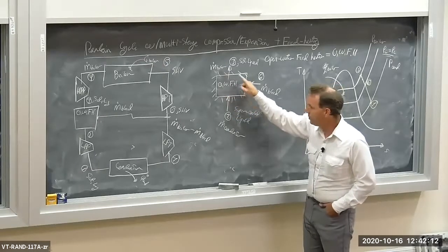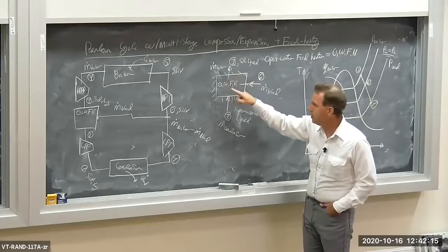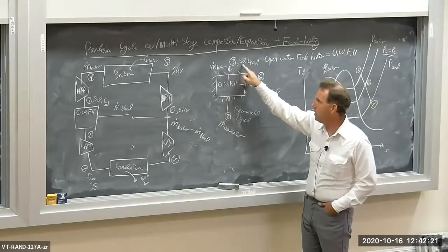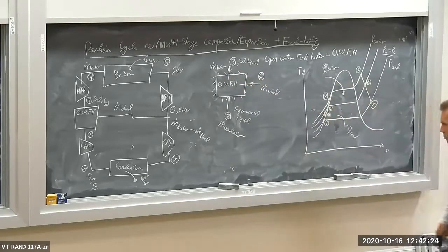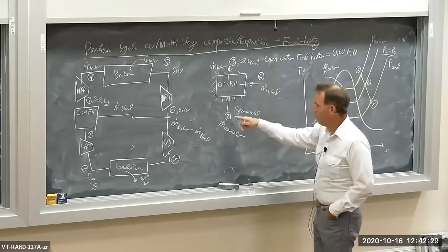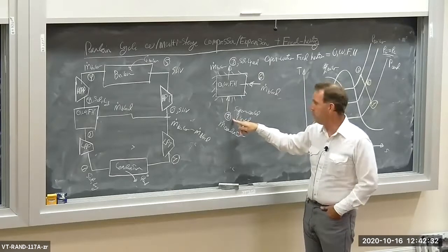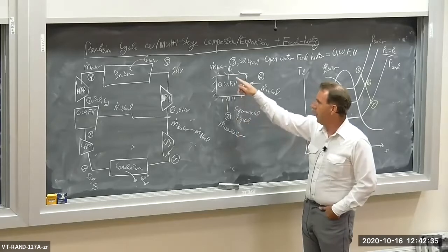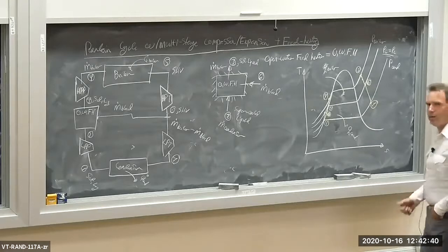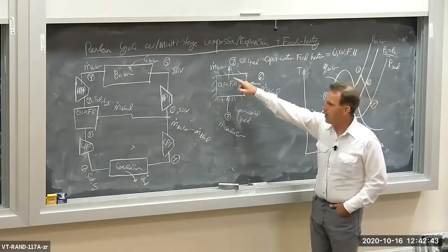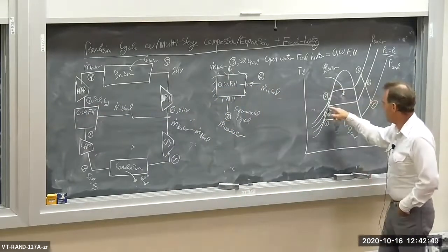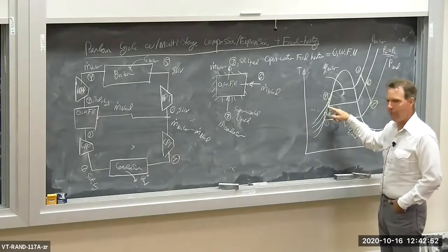We're going to mix it isobarically in this open water feed heater. And that's going to push us up to state 3. It's going to heat up the H2O at state 3 to a saturated liquid. So we're going to take high energy steam, and low energy, or low enthalpy if you like, supercooled liquid, and we're going to heat it up to a saturated liquid. So we're going to increase the enthalpy of the flow going into our high pressure pump. So we end up with a saturated liquid at state 3 going into the high pressure pump.